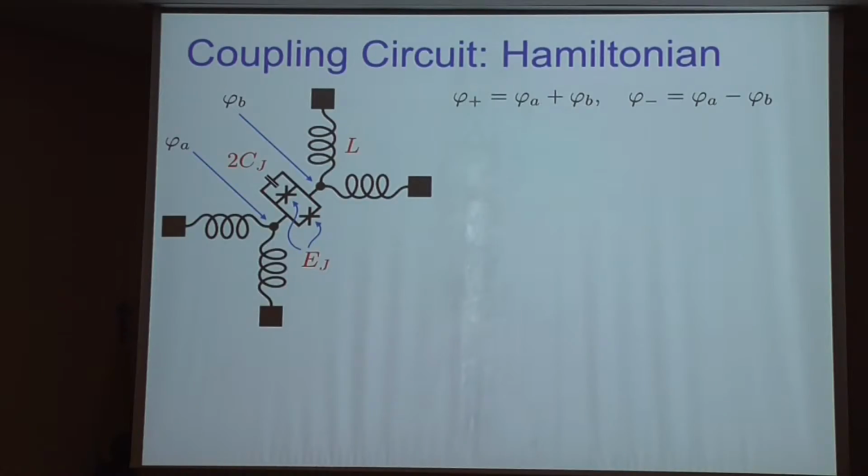So what's the Hamiltonian that describes the circuit? For describing the SQUID element, it's best to consider the center-of-mass and the breathing node for these two auxiliary nodes. That's because the center-of-mass node doesn't couple to the Josephson energy and doesn't couple to the capacitance here, and that's why it will typically be at a very high frequency, and I'll forget about this one in my presentation.